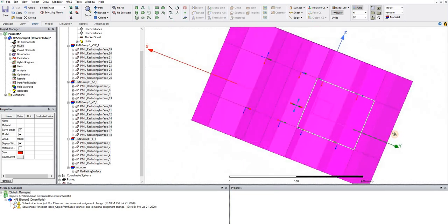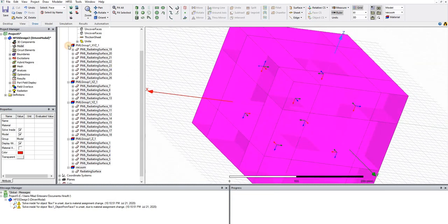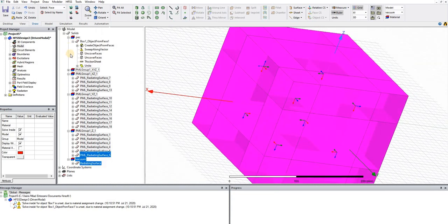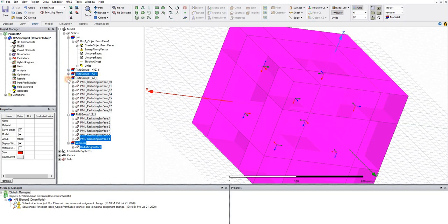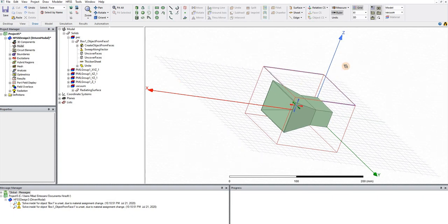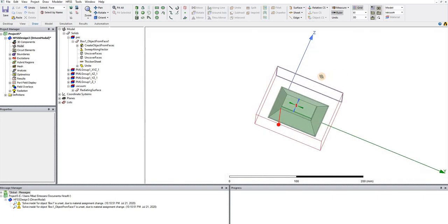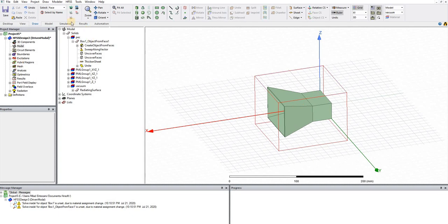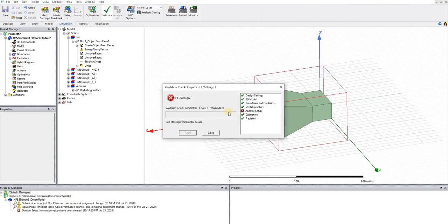You can see the structure here, and it's another way to use a boundary condition which is perfectly matched to the open region on the other side. There's this other technique to use a boundary condition and solve, especially for a larger structure like the horn. And right now this is PEC, and let's validate.